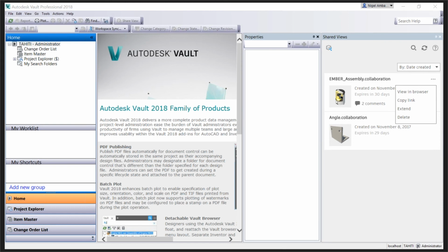Yeah, so one thing to note when you're doing this shared view is, when you're completing the share, let me move over so I can see this other screen. I'm actually working off of 3 screens right now. If you are doing a share, it's going to lock up your Vault while it's converting and uploading that file. So let me go ahead and do that.